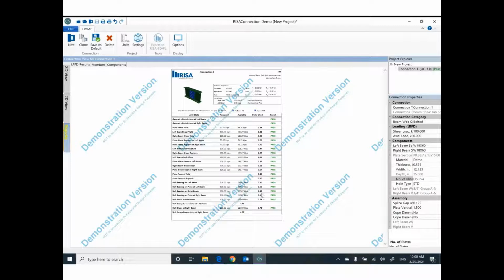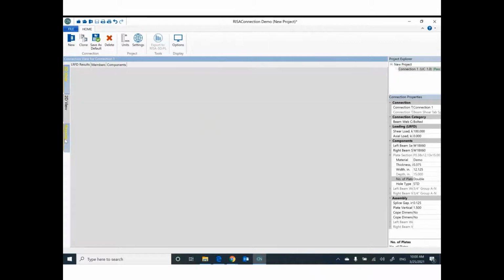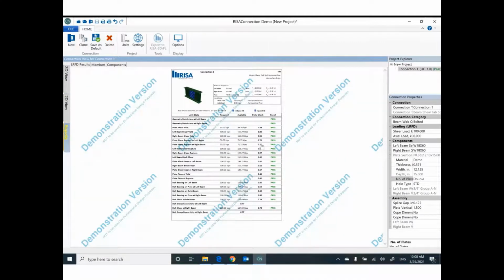If you try to change anything, this number will be close to 1, but this one will be unsafe. We need to keep all of these numbers safe and economical. So this one, 0.97, is safe, and economical, being the highest one. We are good. We cannot change anything anymore. Even if you have a number 0.59, I cannot change it, because if I change something to satisfy this condition, this one will be unsafe.